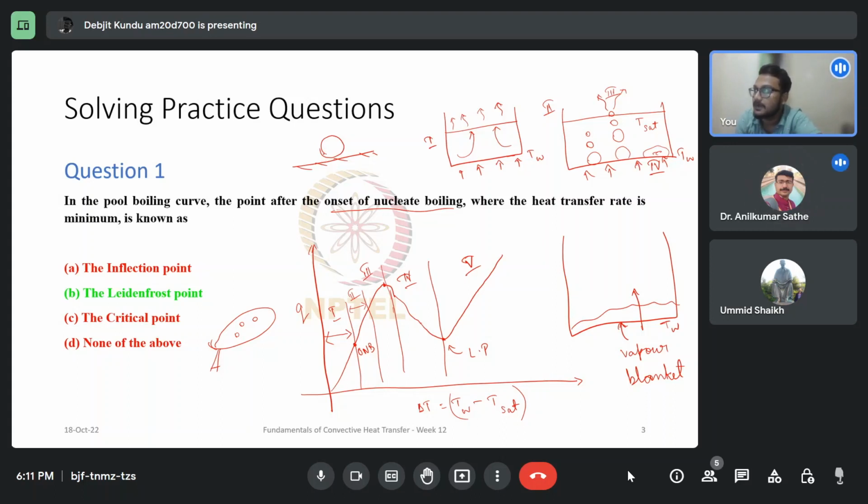In the bottom part of the droplet there are bubbles, and a vapor blanket forms just beneath the droplet, in between the droplet and the hot surface. Any questions? Okay. Anyway, this vapor blanket forms, and as a result, this droplet does not immediately vaporize, and it keeps on dancing on the pan for a certain period of time.